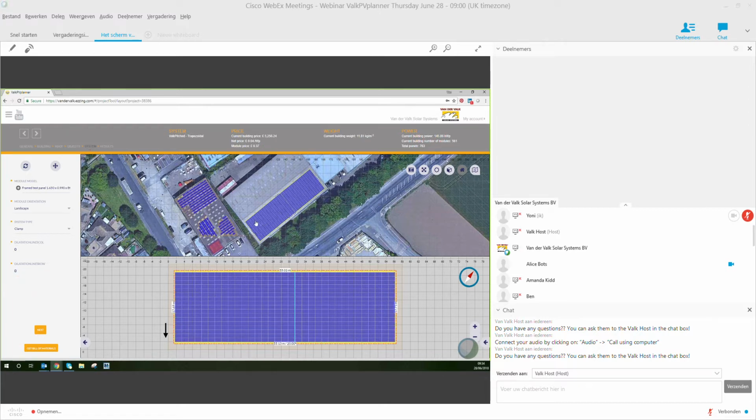So again, with the keep outs, if you had a skylight here, you would have added that at the beginning. If you haven't done that, you can still remove panels just by clicking and holding, same as we did on the flat roof. So we maybe have some very big skylights here. And you can also still remove entire rows and entire columns with the shift and control features.